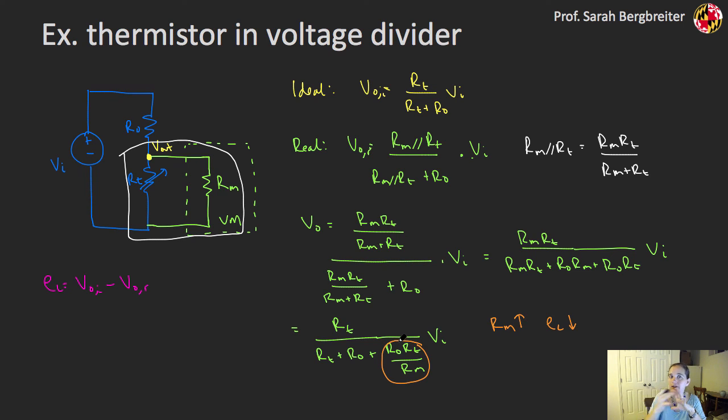In that way, I don't load down that voltage or whatever it is I'm trying to actually measure here. And so in order to do that, I'm going to use things like op amps, and op amps configured as unity gain buffers, and those are going to be providing very, very high input impedances so that I don't have to worry about a voltmeter and an analog to digital converter actually loading this down.